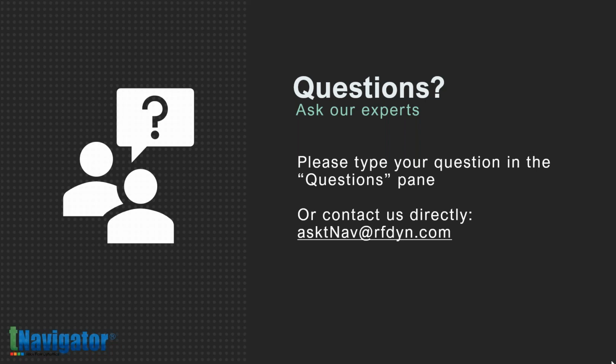Let me go through some of the questions real quick. One of them is, can this be used to predict fracture propagation? That's a really good question. Currently, tNavigator Geomechanics considers the elastic regime only. So, for example, the Mohr-Coulomb or Barton-Bandis criteria could provide information on fracture initiation. Meanwhile, our developers are also working on improving the functionality to expand applications into fracture propagation for unconventionals.